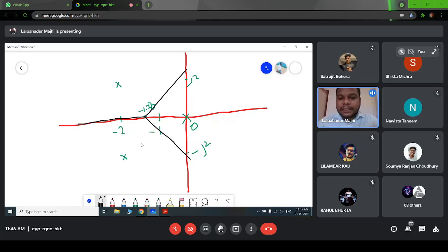So next we have to see from where our root locus will start. Okay. So we know the root locus starts from the open loop poles, and it will terminate either at infinity or at a zero. So we don't have any zero. So all the root locus branches will terminate at infinity. So we have to see at which point. For this real axis, if we choose any point on this negative axis, that path will be on our root locus. Clear?